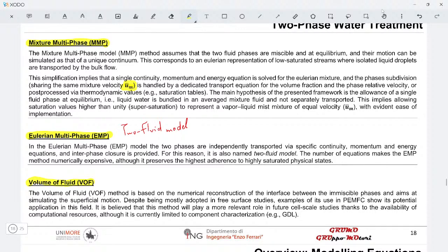these are also used in navigation issues. If you want to simulate a boat using CFD, imagine that you have to numerically reconstruct the surface between the water and the air. You would want a high mesh resolution around the interfacial surface. Okay, so with the development also of adaptive mesh refinement algorithms, which today are more or less present in all CFD codes, the volume of fluid method will have a much wider popularity in the future years than what it has received until now.